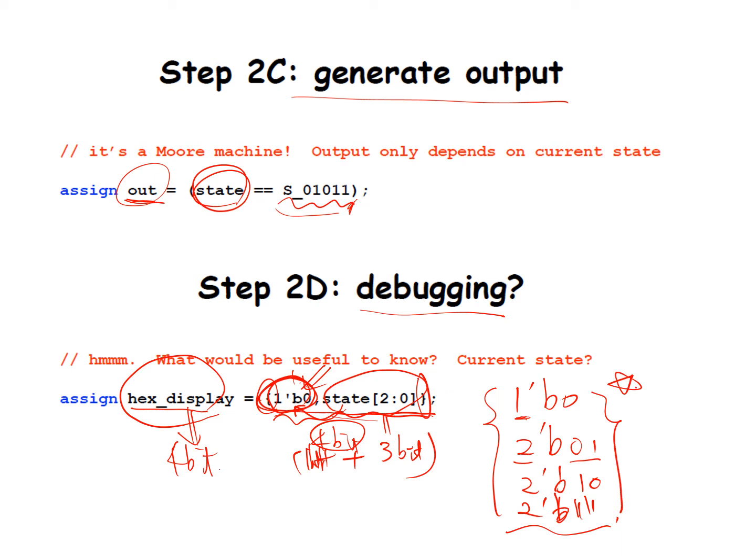Instead of describing it like 0, 1, 2, 3, all these decimal numbers are actually not interpreted and not used. The machine actually takes the binary number, so we prefer to write 2'b00 and 2'b01 and 2'b10 and 2'b11 like that. So you try to describe decimal as binary in Verilog.